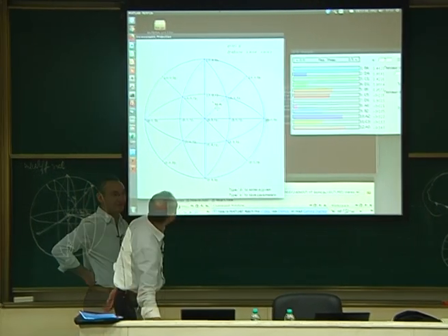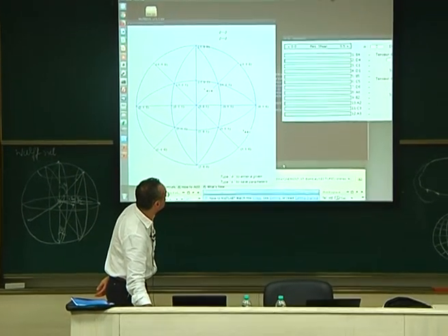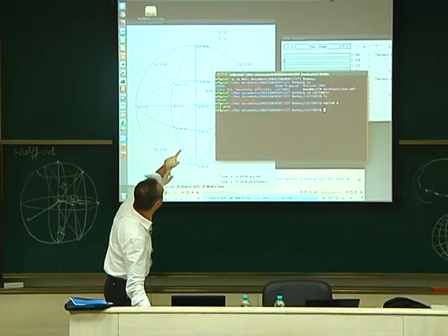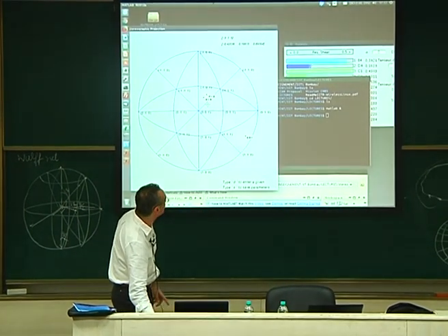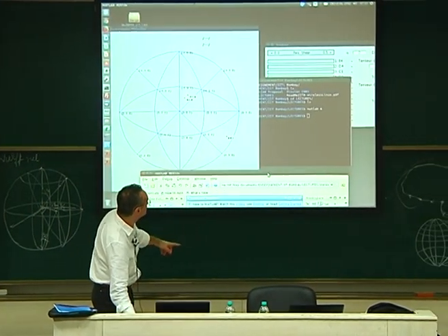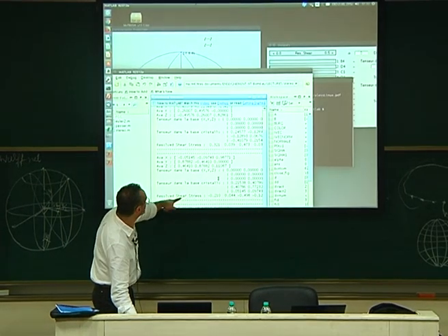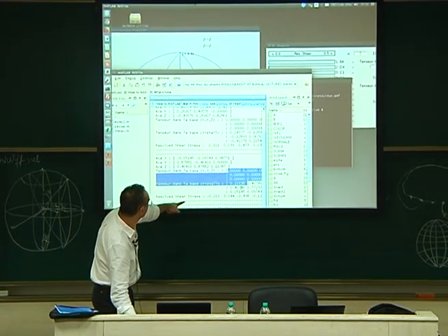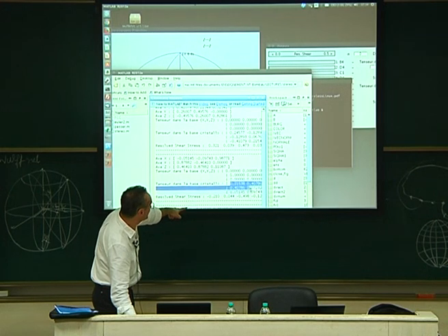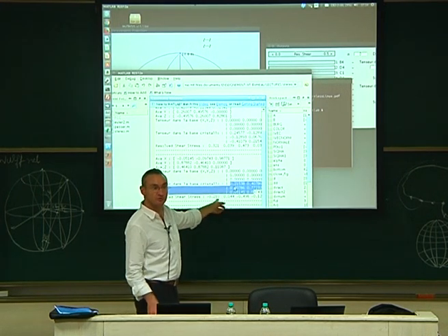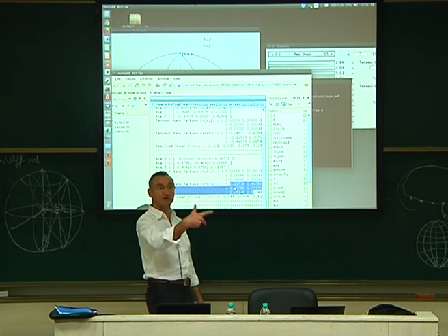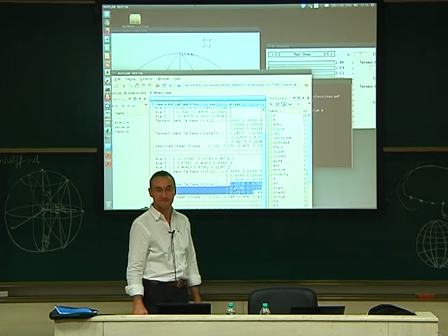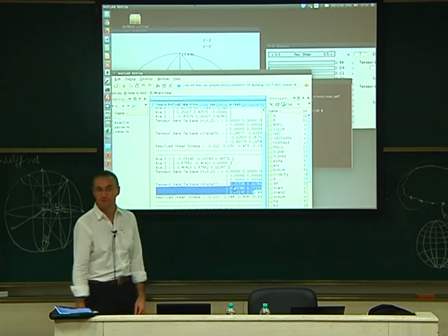Again on the same map, you click on it, and then you have your data. So this is what you take. You say, okay, I want to do DD simulations. I want to pull in that direction. Here, you click on it. You pick up your stress tensor, which is given here in the crystallographic axes. You put that in Paradis because you're using Paradis, and you will have your loading corresponding to that. Without any rotation, it's already done for you. Okay? That's a tool that you can use.